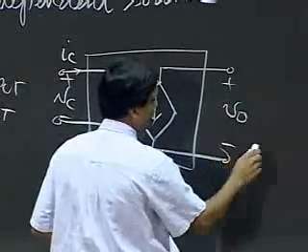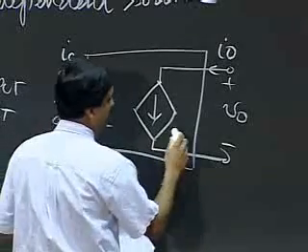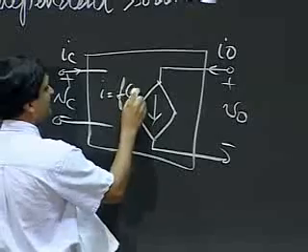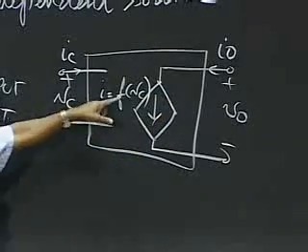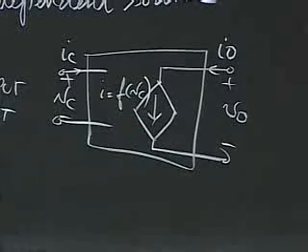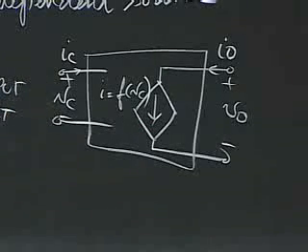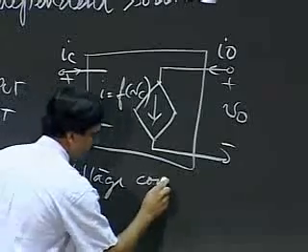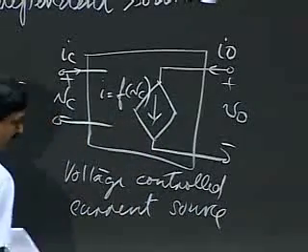I can apply the corresponding output variables, I0. And I can say that the current I is some function. In this example, I've designed the example so that the current through the current source, I, is some function of the input voltage or the control voltage VC. So notice that the current through this current source, I, is some function of another variable. In this example, it's the voltage across its control port. Not surprisingly, this device is called a voltage-controlled current source, or a VCCS.